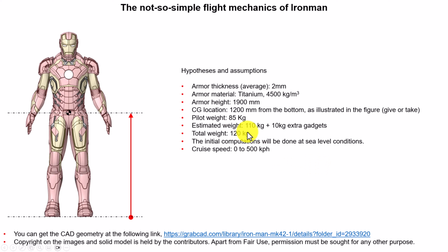The most important one, and I think it is very conservative, is the weight of the whole stuff. Weight and height, but most importantly, weight. This is the one that is going to drive the design, how to generate the lift, the drag, and everything. So we assume 120 kilos after some design using space claims, assuming thickness of the armor, material, and so on. Personally speaking, I think it's very conservative, should be at least twice, but let's bear with this.